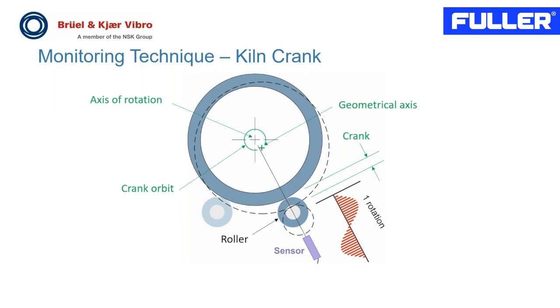To monitor this, we use inductive distance sensors positioned below each of the rollers. And from this, we detect the cyclic variation of the distance and the amplitude.